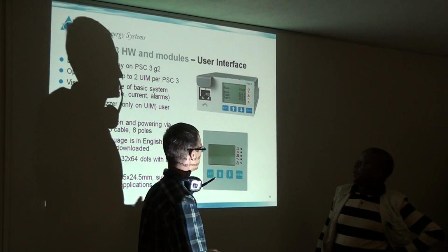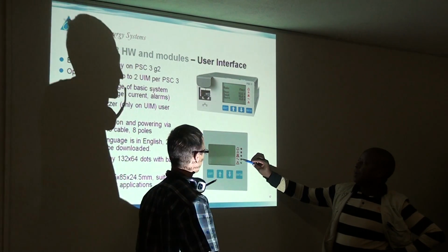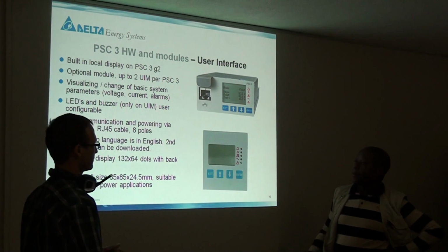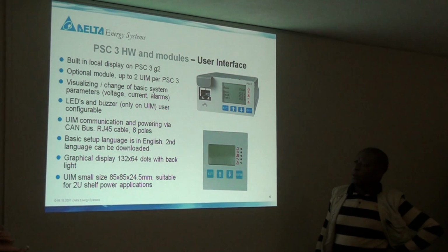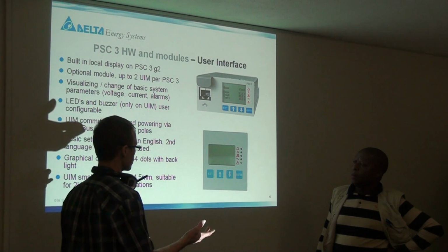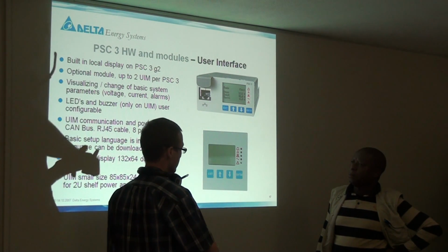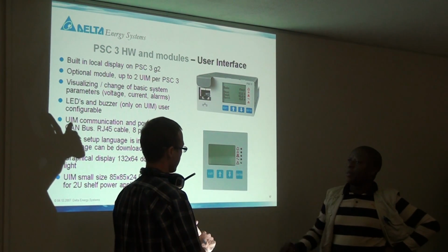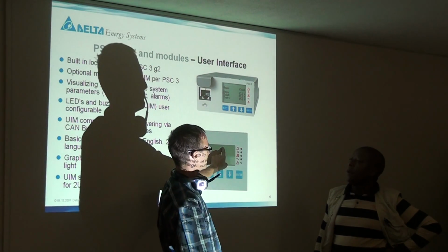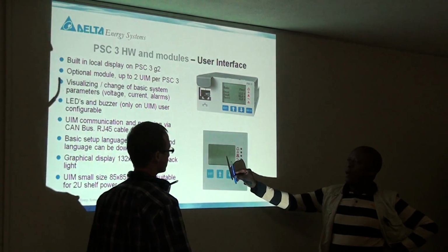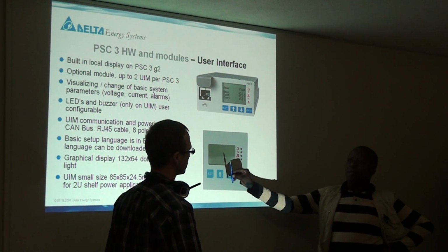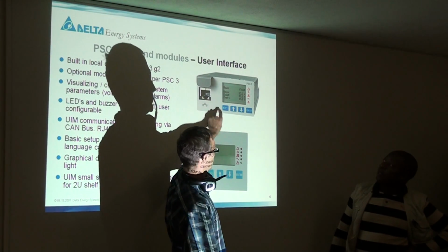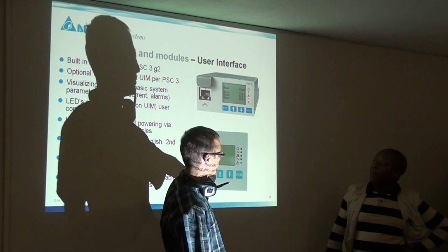Okay. This is mains fail alarm. This is the alarm. And then this is that special function. Any special function like a battery test that's been forced, boost charge, an initialize or equalize charge, or an event control function can show you in the display. The moment this comes on, it will tell you what new event is happening here. It also has a buzzer. This has a buzzer, this does not. So you can switch the buzzer on and off. It's quite irritating. Most people switch it off.